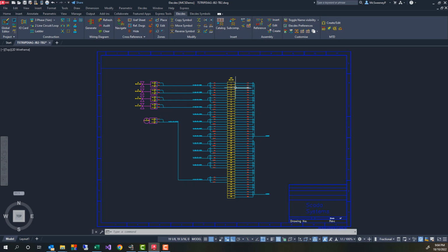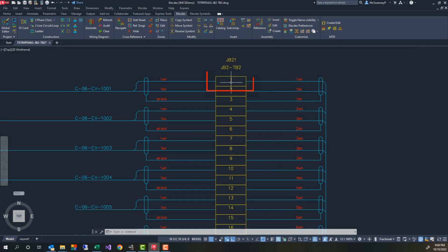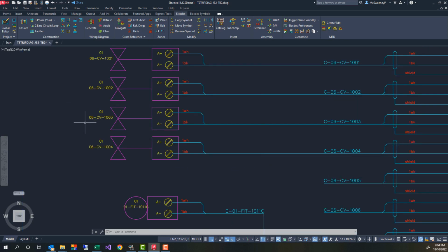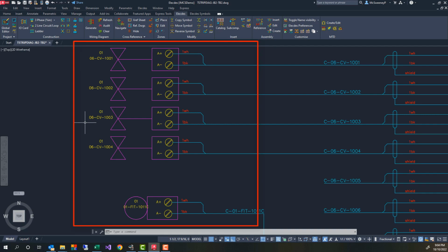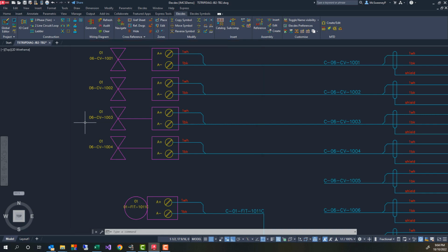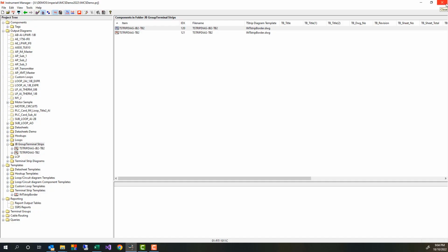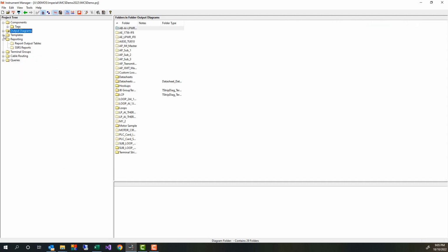The EDS wiring diagram generator builds components in a Lego style. Terminals and wire markers are made from a small template symbol. The instruments are positioned to the left of the terminal strip. Each instrument can have its own wiring diagram template symbol, your choice of graphic. Where practical, cables are drawn between any connected components on the diagram. All base template formulae, including the title block formulae, have been loaded from the diagram record within the database.